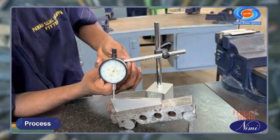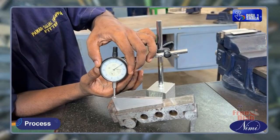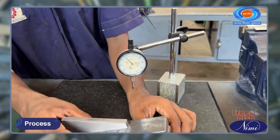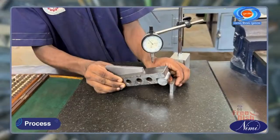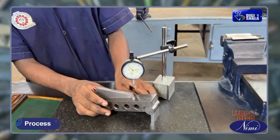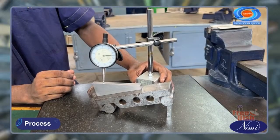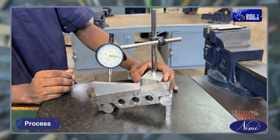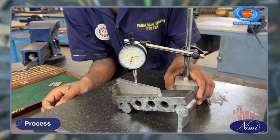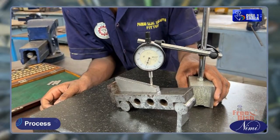Set the dial test indicator plunger on the angular surface of the jaw. Set the dial test indicator pointer to 0 position. Bring the slip gauges under the sine bar roller. Move the dial test indicator from one end to the other end and check the parallelism of the angular surface. If the dial test indicator pointer does not move to the plus or minus side and stands still at 0 position, it means there is no deviation in the angular surface of the jaw.